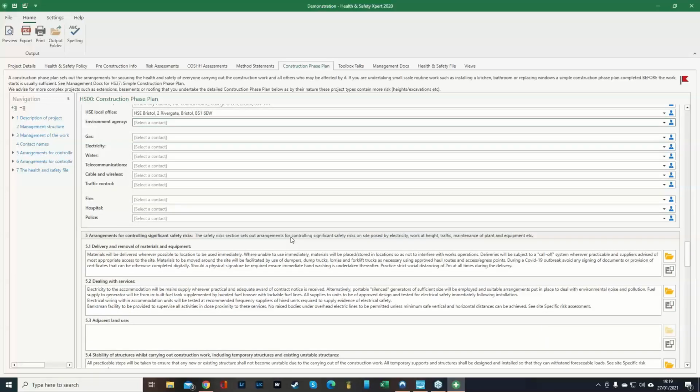So if you are shutting off roads, who you're dealing with when it comes to traffic control. But gas, electricity, and water, that's more in case you are actually going into the ground near mains or major pipework. Because what should happen is if you've gone through one of them accidentally, contact the company that's their supplier, and that way you can make sure that it's all being documented by their team of engineers. So you want to make sure that you're not liable for that information.